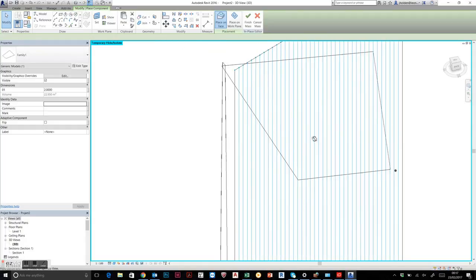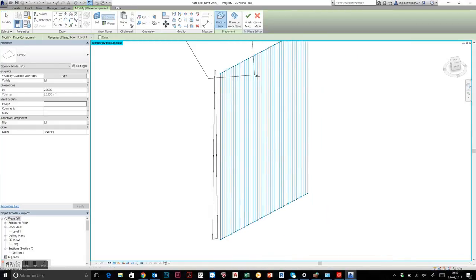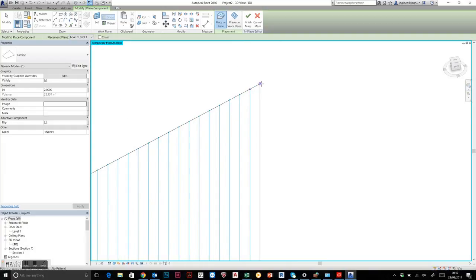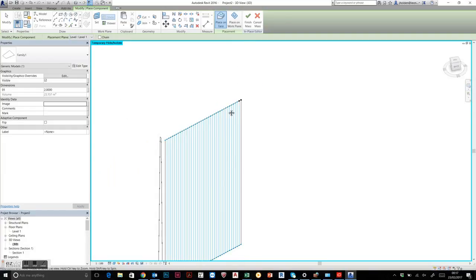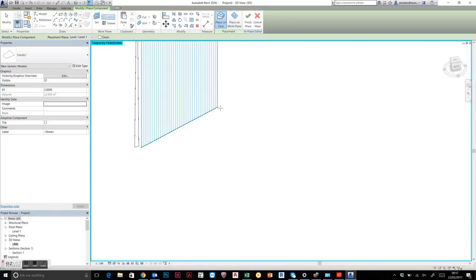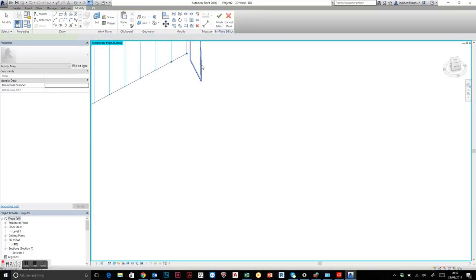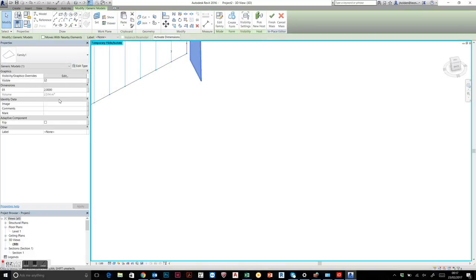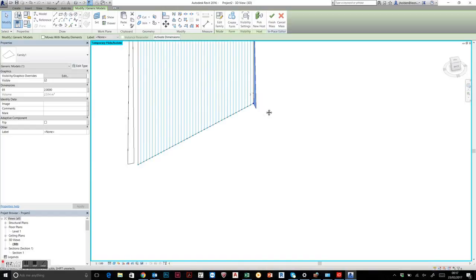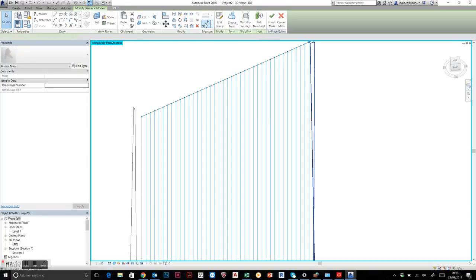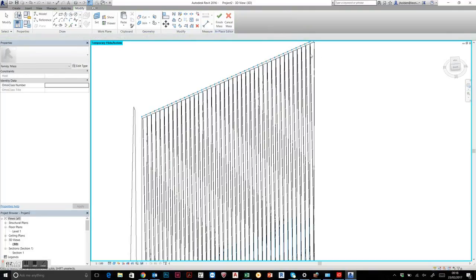When you click create similar, for those who don't know, you are creating a family with exactly the same parametric routines on board. So you don't have to go back in and reprogram each individual one. 1, 2, 3, 4. So to that point, you'll see that this guy is still reading 2 meters. One of the cool things too, if I hit pattern repeat, it kind of dumbly goes.